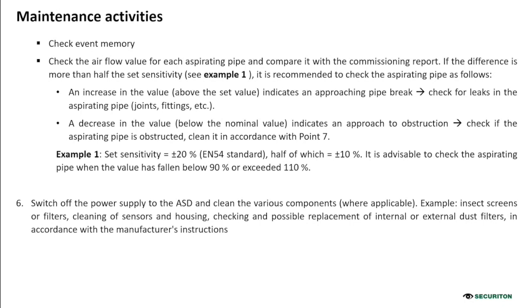If after the maintenance, after cleaning the pipes, which we will see how to do, and after changing the filter, the airflow still does not come back to the nominal value, you can check the airflow sensor. But you need to do it carefully because the airflow sensor is very sensitive and very easy to damage.